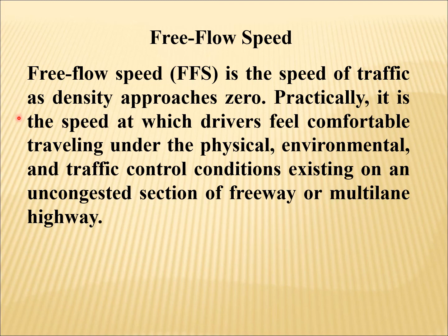Practically, it is the speed at which drivers feel comfortable traveling under the physical, environmental, and traffic control conditions existing on an uncongested section of freeway or multi-lane highway. So here you can see these words again, that free flow speed is the speed of traffic as density approaches zero. So it is denoted by FFS.